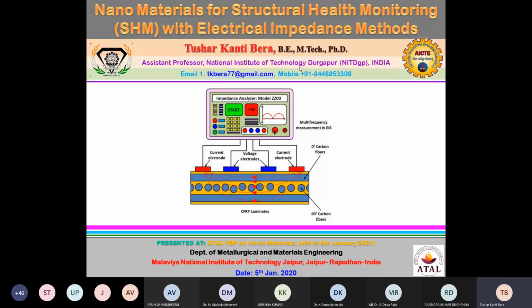The impedance based monitoring technique is comparatively new, where the material's impedance, fully called electrical impedance, is monitored. So we will discuss the electrical impedance based methods, and then gradually move towards how nanoparticles can be helpful for electrical impedance methods.